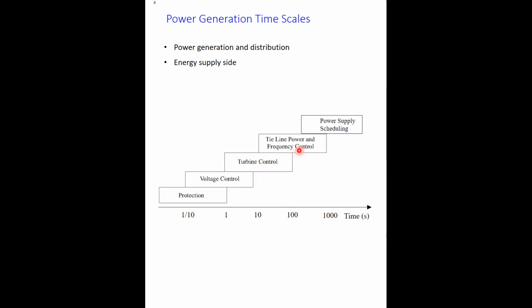Then the load frequency control, which is in the secondary loop, has information even about the tie-line power. The secondary loop for frequency control, compared with the primary frequency control, acts over a larger range of time duration. So here it could be a few minutes to several minutes.